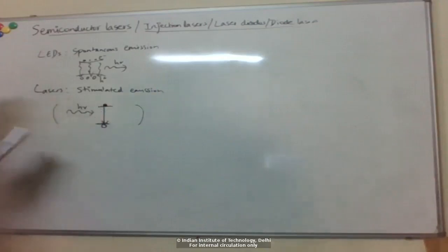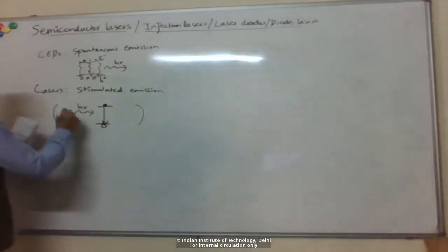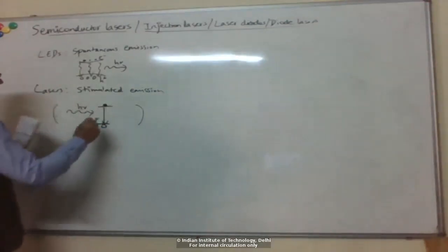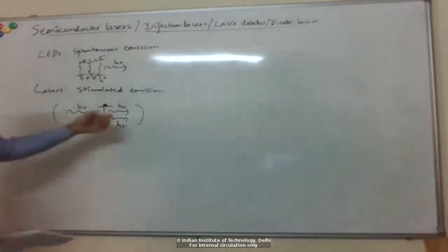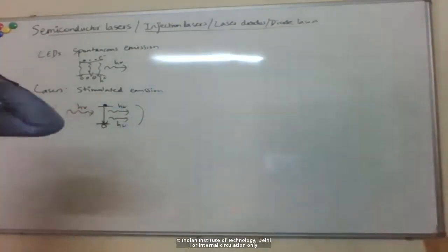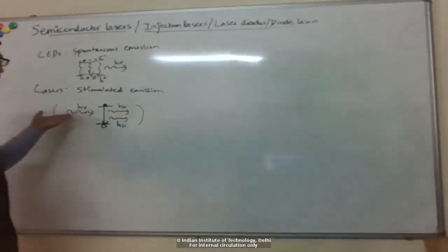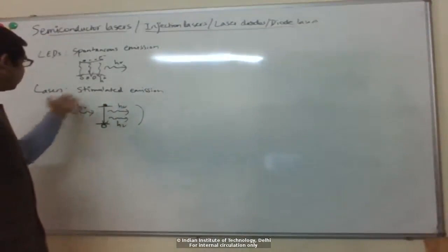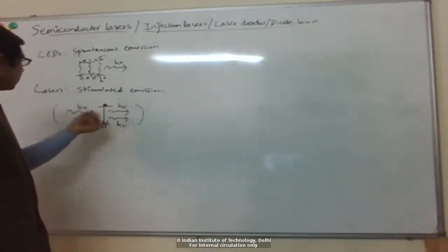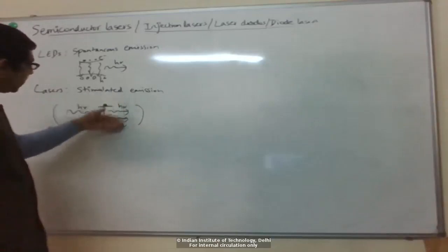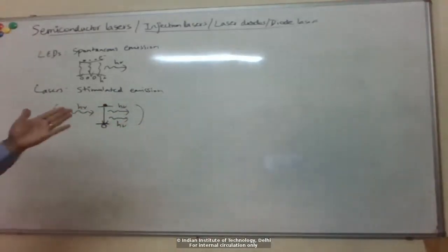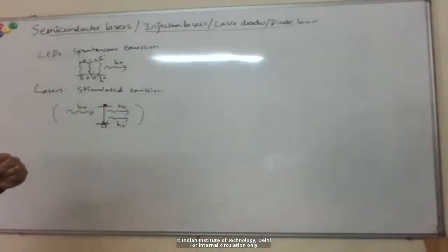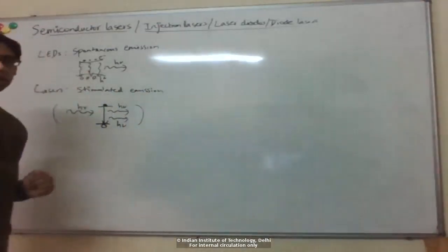And what happens is that a photon within this laser cavity can stimulate a recombination event, and generate another photon to be emitted which is identical to this incident photon, right? And so if this process happens with many carriers and happens many times over, you get lots of photons with the same frequency and the same propagation direction. So you'll get a bright coherent beam with a well-defined frequency and a well-defined direction of emission, unlike the LED.